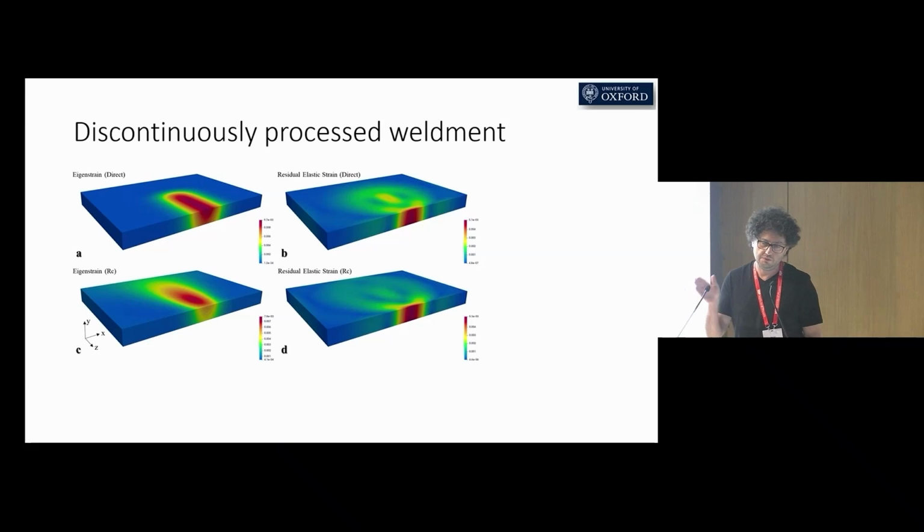Before doing that, we performed a numerical experiment. In this numerical experiment, we imported an eigenstrain state with 3 components distributed in all 3 axes and calculated residual elastic strains belonging to this eigenstrain distribution. And we did a similar cutting process, but this time numerically, from the front face of the domain only, and performed reconstruction.